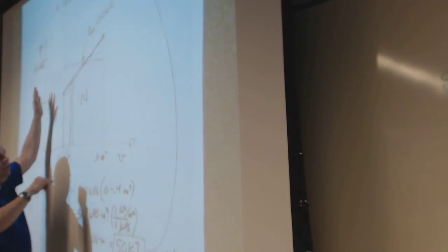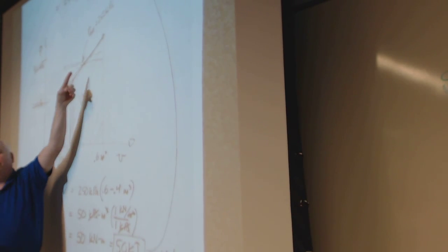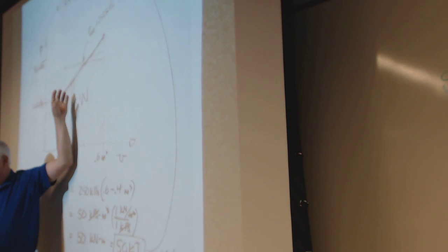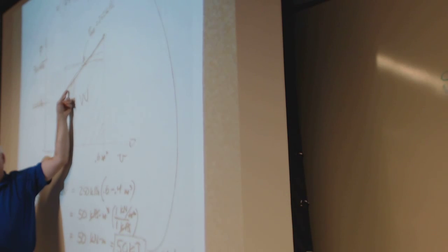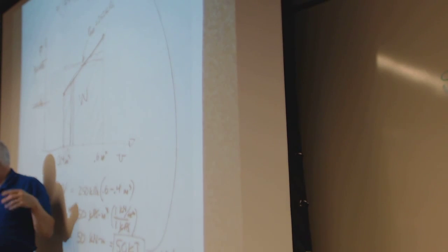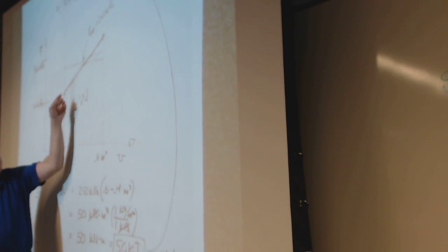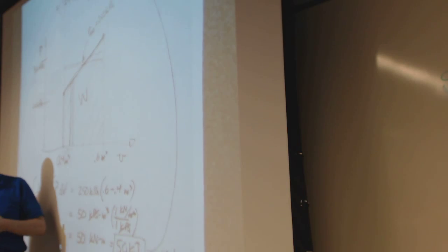They wanted you to put out a pressure volume graph so you could see if it's a linear spring, this is going to be linear. If it was a nonlinear spring, this would have more of a scoop to it, and you need to know more information in order to get the curve of that line. It would make a difference if this line had a scoop that way or a scoop that way. The area under here is work, pressure times volume.